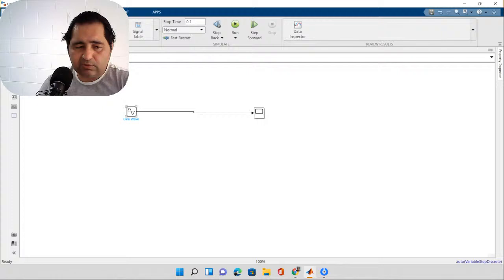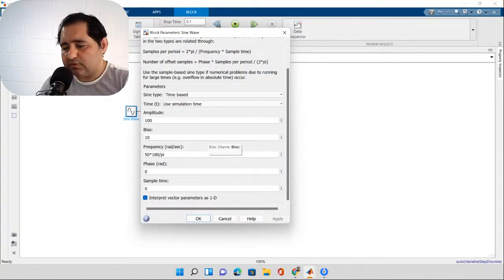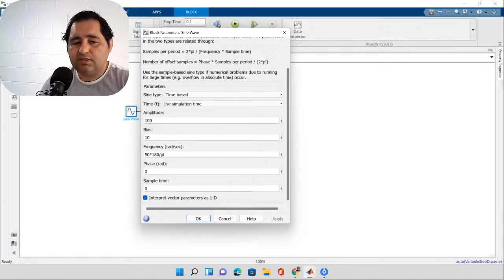Actually, in the real world also, if your analog to digital converter doesn't have enough samples, you're not going to get a good signal. Well, sample time was something random, I can say random, by putting 0 here. But now we can actually decide how much our sample time is. So say, for example, 0.0001. Okay, so it's 1,000 samples.